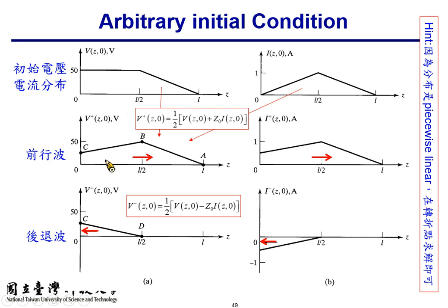And you can imagine for signal C over here, it will move forward to the right, and the left end of the CD signal will also get reflected from the left hand side, and because it's open-ended as well, the reflection coefficient is 1. So this part will follow up the forward-going signal and proceed to the right. Okay, so it's kind of a circulating signal.